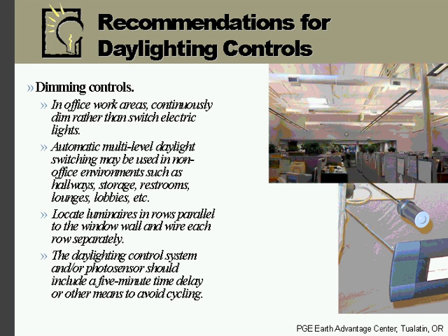The recommendations for daylight controls. So we're going to dim our fluorescent lights in the open office areas, in the window wall areas where we have skylights. We really want to dim instead of switch electric lights off in response to daylight. We're going to get better energy savings, but primarily it's because of user satisfaction.